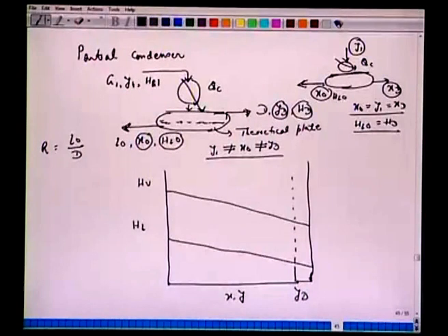Once we have this YD, let us mark HD and X0 with HL0. First we have this tie line. This enthalpy here is HD, the saturated vapor enthalpy, and here we have X0 or XL0. X0 is the same as XL0, and this enthalpy here is HL0. We can also mark this delta D.